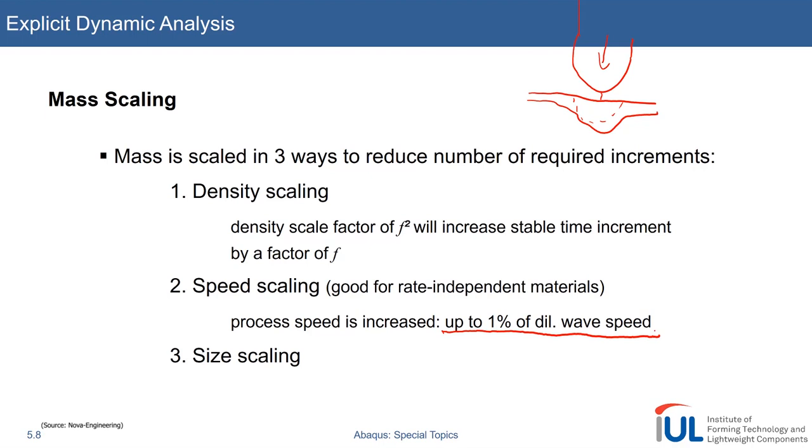As an engineer, you have a natural feeling that most of the materials out there have a rate-dependent material response. And this is actually true. But if you neglect these rate-dependent responses and assume instead a rate-independent response, that's why I said it feels a little bit unnatural, then the punch speed actually doesn't matter.